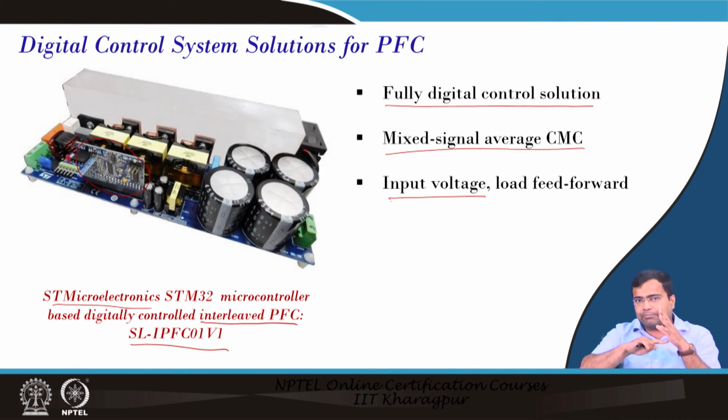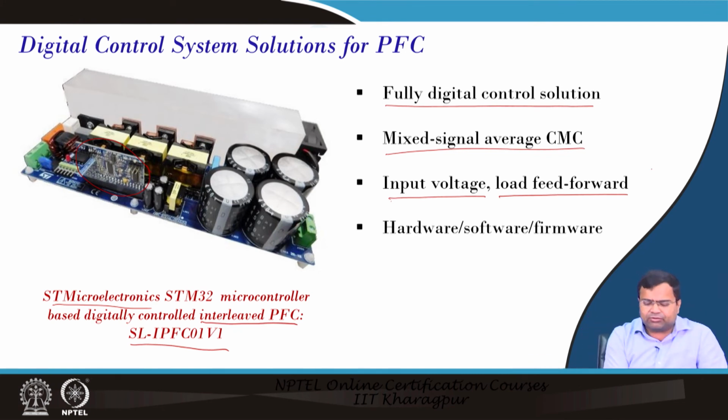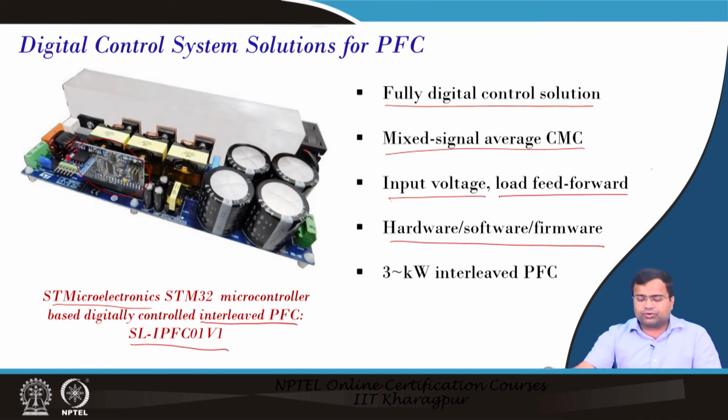So, the shape of the reference current should follow the rectified input voltage. That is why input voltage feed forward is essential, and this IC also uses a load feed forward, because you want to achieve very fast transient response. And this particular solution also offers hardware, software, firmware integration. This design demonstration is for a 3 kilowatt interleaved PFC, and it also offers very high efficiency.